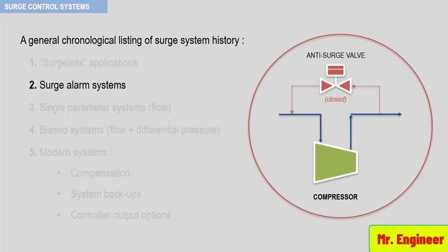Therefore, the surge system is simply an alarm or shutdown system that will stop compressor operation in the event of surge, thus protecting the machine. Be aware, though, that a full assessment should be made to determine the cost impact of such a shutdown and the potential problems incurred on the startup. A properly installed surge alarm system can eliminate these unnecessary shutdowns.